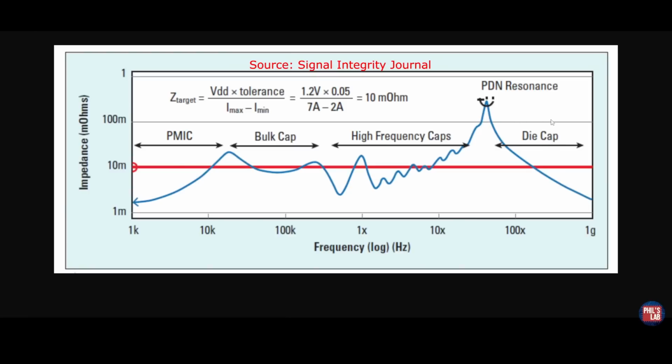as we'll see later on. Now, you can see already here we might have some resonances where, for instance, the traces and capacitors resonate together, or you might have some troughs which are to do with resonances, for instance, the self-resonant frequencies of capacitors. So you'll oftentimes see parallel and series resonances, and keeping the impedance flat can be quite difficult. And you typically will have some excursions, but it's important to keep those excursions low because they can trigger what is known as rogue waves and introduce more noise at those points. But we'll see that a bit more later on.